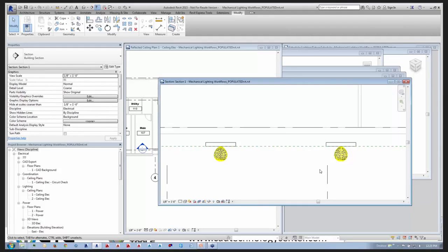You will be able to use these clearance boxes to do that clash, which is a very useful feature. I know a lot of people are very happy to be able to do that. And obviously this process of placing this nested clearance box family into your lighting fixture can be applied to essentially any family and certainly is not exclusive just to your light fixtures.